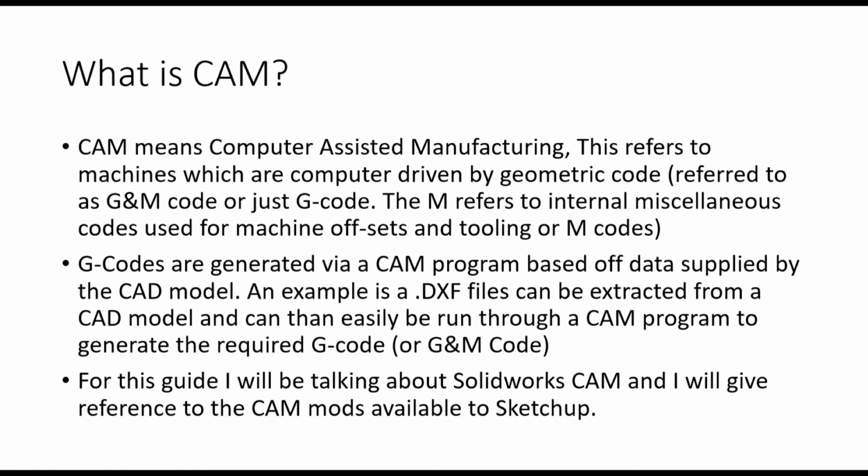Afterwards you're just working with the machine. Sometimes if you've got a machine that doesn't have enough suction on its bed, or it's nesting smaller parts out towards the edges of the sheet, you still really need to work with the machine, hold those parts down as it's cutting, or help the machine out a little bit. So I think you get that bit. That's just the CAM side.